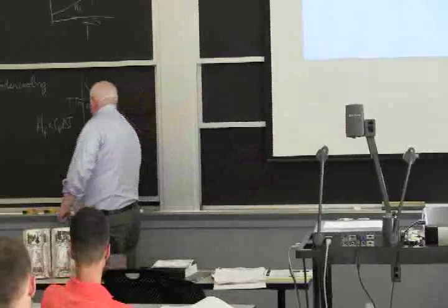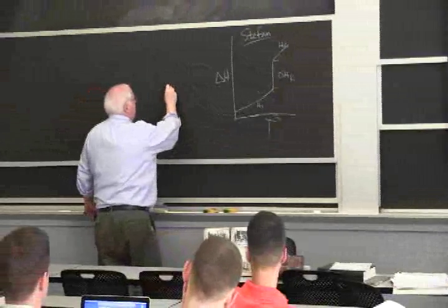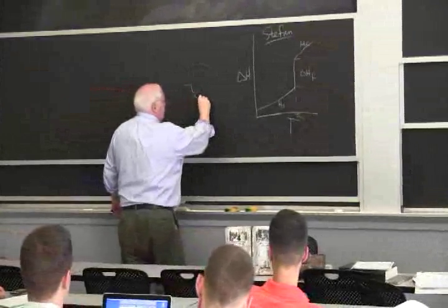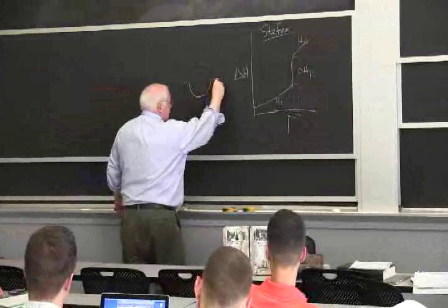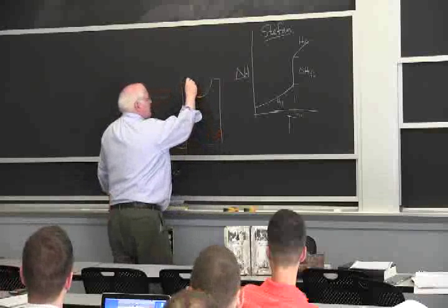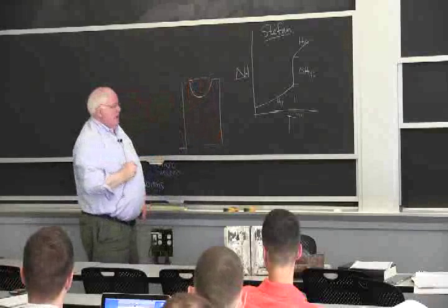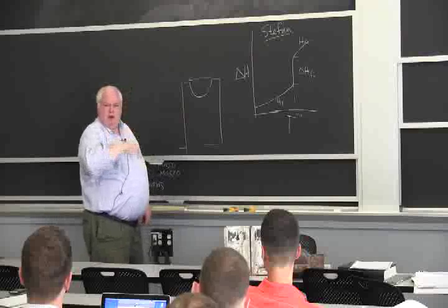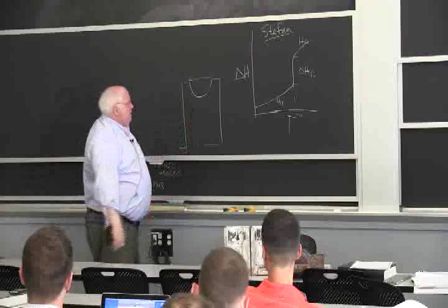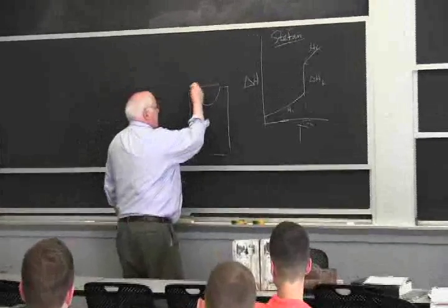It's like a railroad wheel, if you will, a great big railroad wheel, and the edge of the wheel has a mold cavity in it. The diameter's down here, and this might be about 2 or 3 inches wide. So this wheel is just going to go around in circles. It's water cooled, so you can extract the heat of fusion, and they have a steel band.